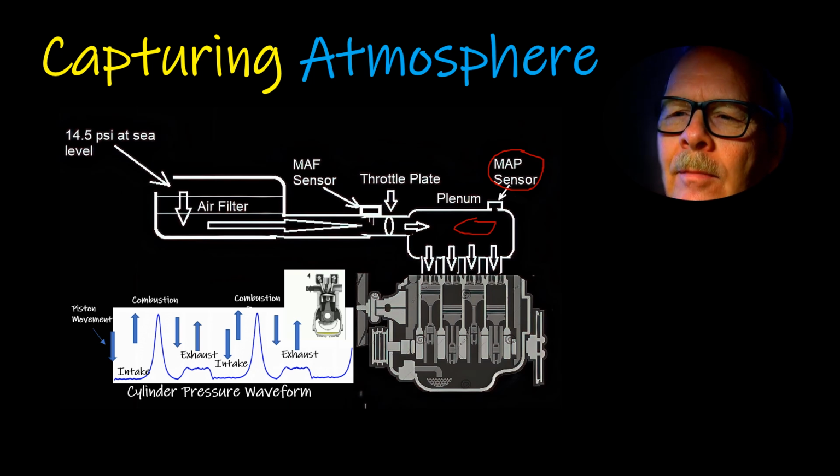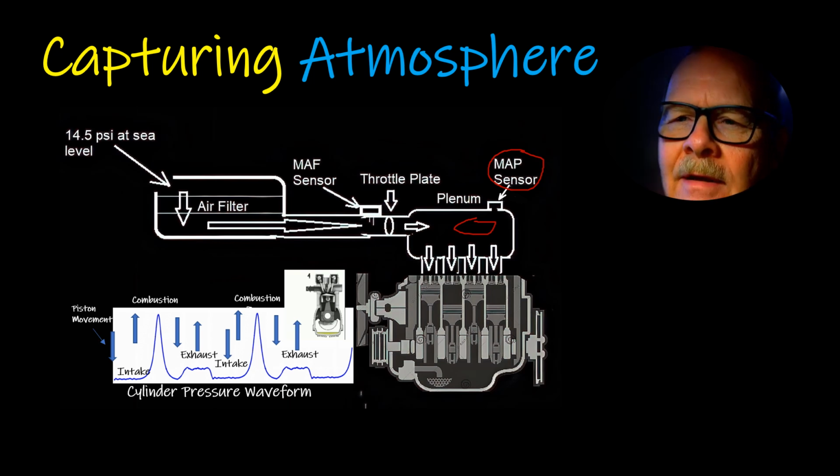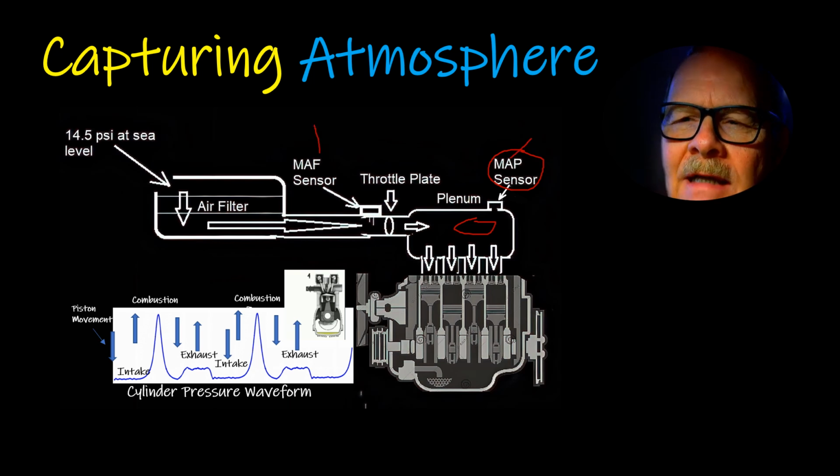Of course, your throttle plate, like I say, creates the restriction. Diesels, unless they have got a throttle plate that's there to help with EGR flow, diesels won't have a throttle plate, not typically. The mass airflow sensor, a lot of these engines now, for a while they tried to do away with the MAP sensor and replace it with the mass airflow.